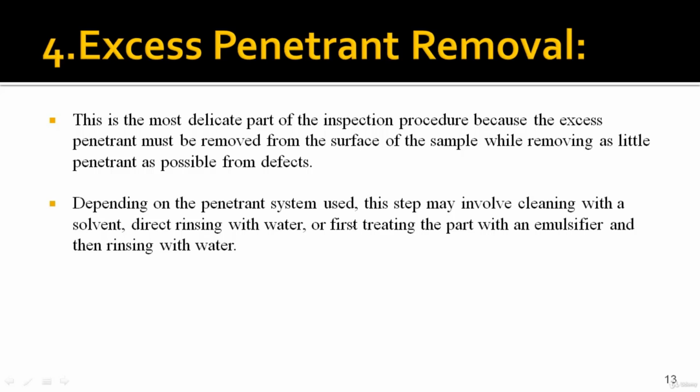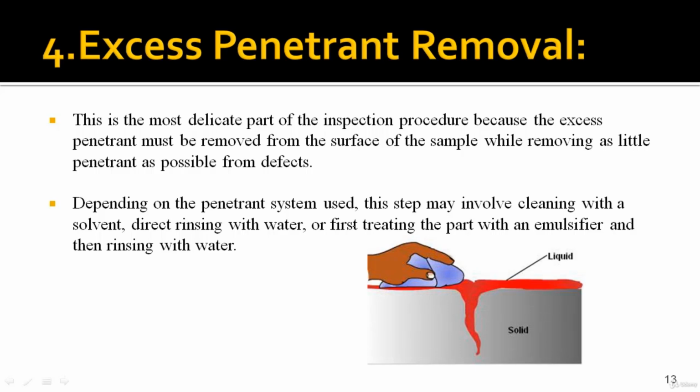Depending on the penetrant system used, this step may involve cleaning with a solvent, direct rinsing with water, or first treating the part with an emulsifier and then rinsing it with water. It depends on what type of penetrant system we are using. You can see in the following diagram that after dwell we will remove the excess penetrant from the surface.